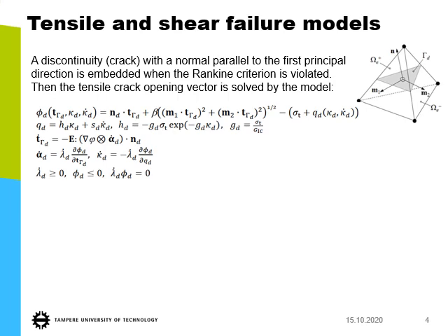Then we have tensile strength and softening function Q defined here as the sum of the softening term and the rate-dependent term, which is defined by the viscosity kind of modulus here, S_t, and the rate of the internal variable. And then there's the softening modulus, which is an exponential one and calibrated by the mode-one fracture energy.